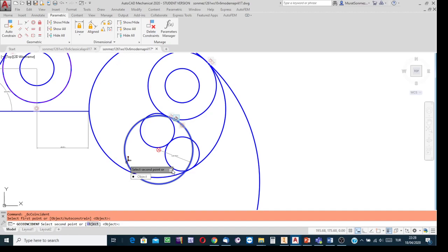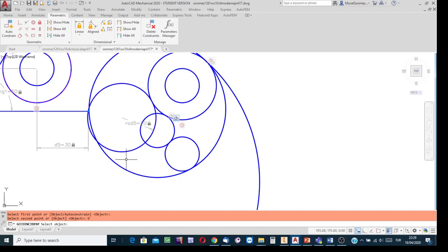The existence of this tiny arrow within the box is a reminder that at this stage there is an option list. In the list there is only one option, Select Object; select it with a click. This is to say that not the center but a point along the circle is to coincide. Click and then indicate the circle.